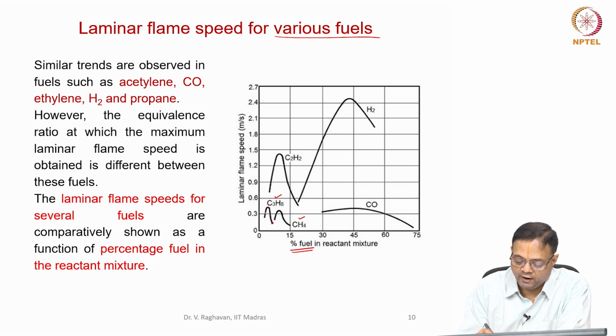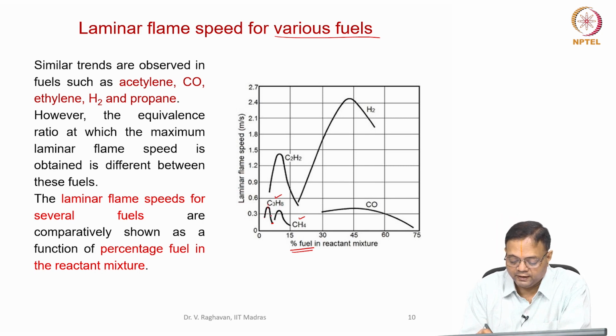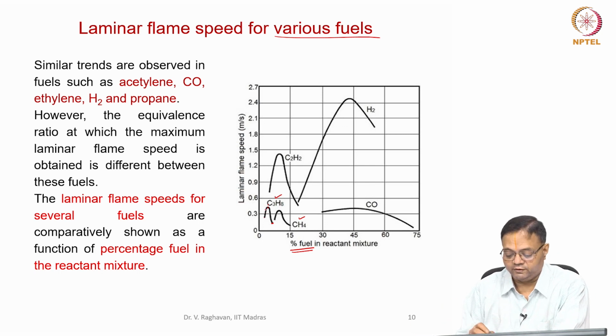And the flame speed increases from the lower equivalence ratio and reaches the maximum at a particular value of equivalence ratio, which is actually at the slightly rich condition, and again decreases beyond the maximum value, where the equivalence ratio is increased further from the rich value to further rich values, say for example 1.1 to 2.5 etc. Similarly, for methane we have already seen this.